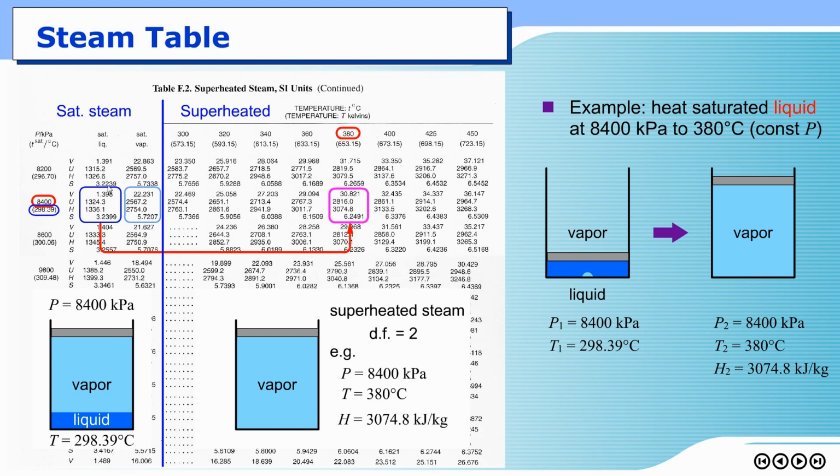Then from the table you can read enthalpy. Enthalpy would be here as 36.1 kilojoule per kilogram. The process takes place under constant pressure, so therefore heat would be delta H, and just taking H2 subtracted by H1, you get the number. But this time the number is about 1,000. It's in the order of 1,000, so it is much higher than previously.